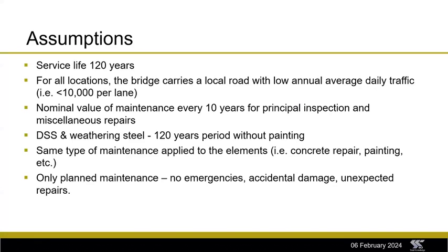We assumed a service life of 120 years. This is what might well be assumed in the UK. I'm not sure what it is in New Zealand. We assumed the bridge carried a local load with a low annual average daily traffic, nominal maintenance every 10 years for principal inspection and miscellaneous repairs. And we assumed the duplex stainless steel and the weathering steel, well, they clearly didn't require any repainting, so they didn't require maintenance for 120 years.